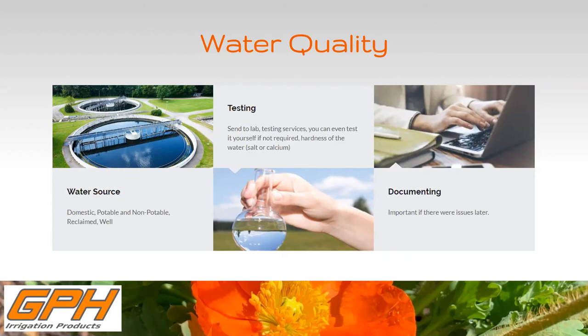I think it's quite important, because I have seen on different projects where the water quality wasn't what they thought, and of course it affects the system in a negative way. Not only the system, but poor water quality will actually affect other things such as the housing, fixtures, and so forth. So it's important to test or get those reports on the water.